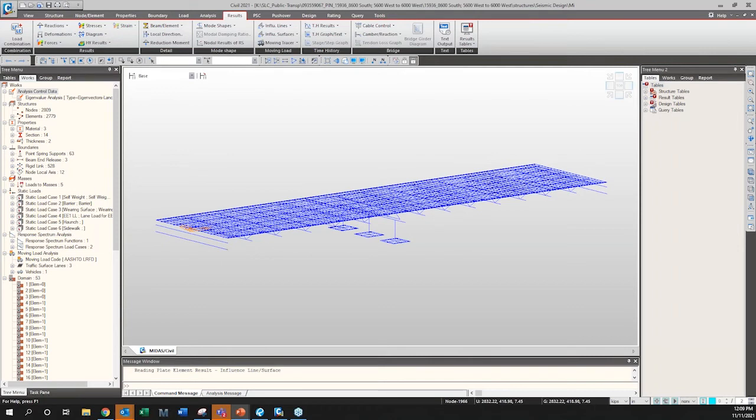First off, getting into why boundary conditions are important. As most of you probably are aware, boundary conditions are fundamental to FEA modeling. And I'm sure that you've all experienced it at one time or another where if you don't have a boundary condition in the right place, your model essentially won't work. You have to have boundary conditions in order to model. And so they really do exactly what their name implies. They establish the boundaries for the behavior of your model. So FEA is at its core a stiffness problem in the end, and without boundary conditions, you can't solve a stiffness problem.